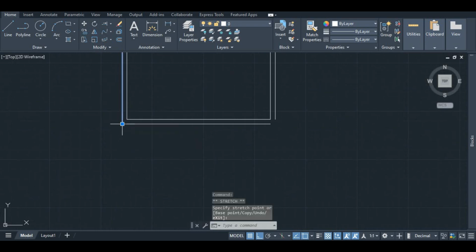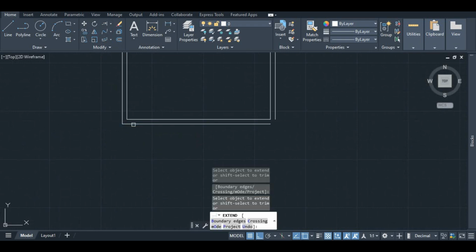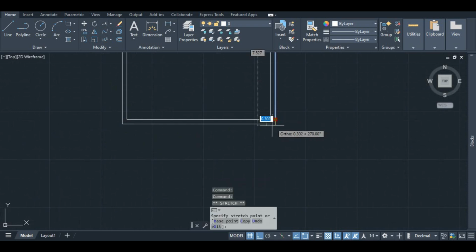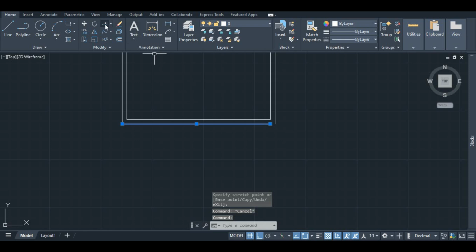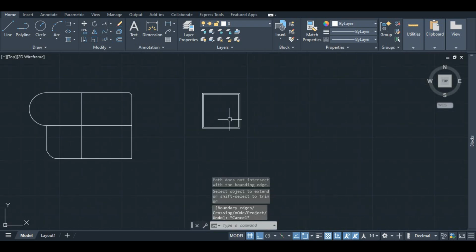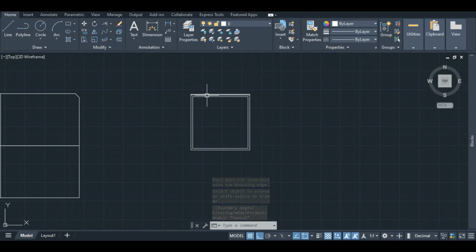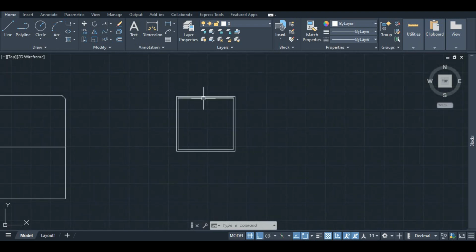So you can take this also, snap here, bring them here, and you can use this to join this to this, and then you can take this and bring it down here. It's still stretch. You are stretching the line, and you take this and use this to press this and then join together, and then we have this wall that has been properly offsetted 225 by 225 by 225.